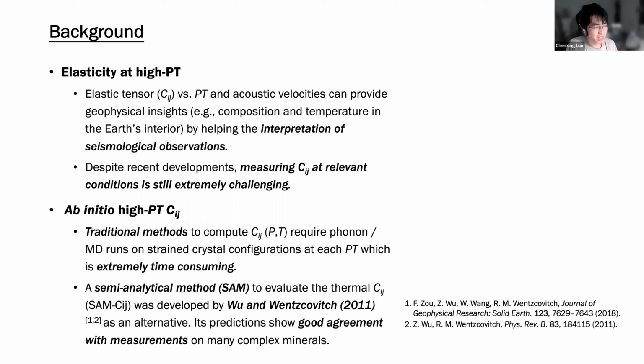So what this method does is reduce the effort to obtain these thermoelastic constants, because we only use the phonon and static elastic coefficients, which I will show you in the next few slides. And that is all we need to obtain these high pressure and temperature elastic coefficients.